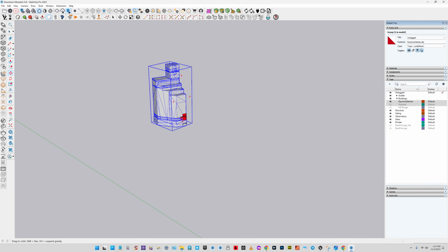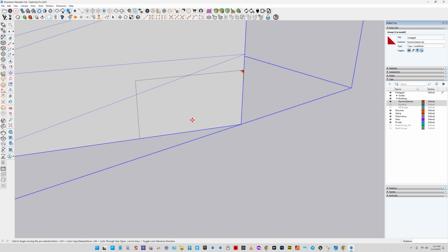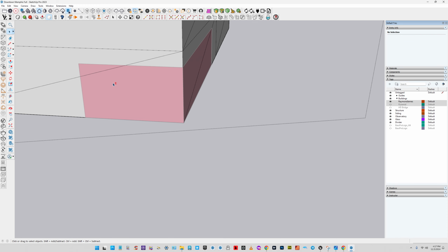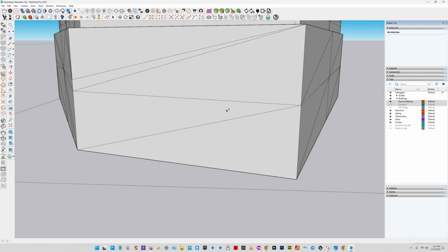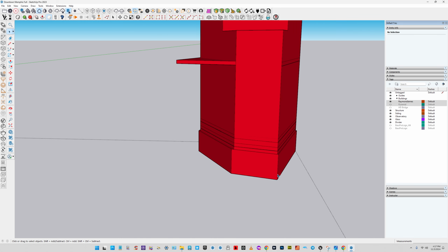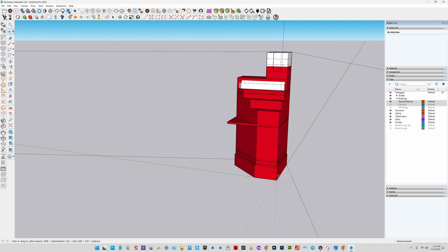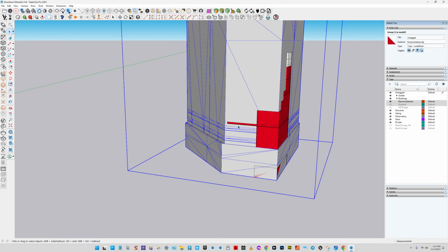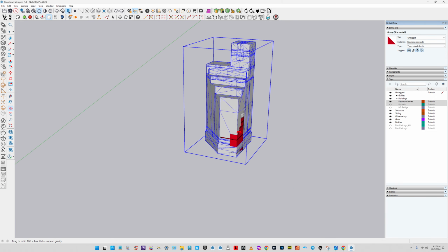Right? And then I'll go into it, double click it, Shift H to hide everything else that's not inside of that group, Control Shift A to change my axis to this corner. Okay, perfect. I'm going to do the same thing for this, Control Shift A, a shortcut that I created to change my pivot point axis. And then, would you like to update the component axis to match your modified sketch? This will change the axis for all instances. Yes. Okay.